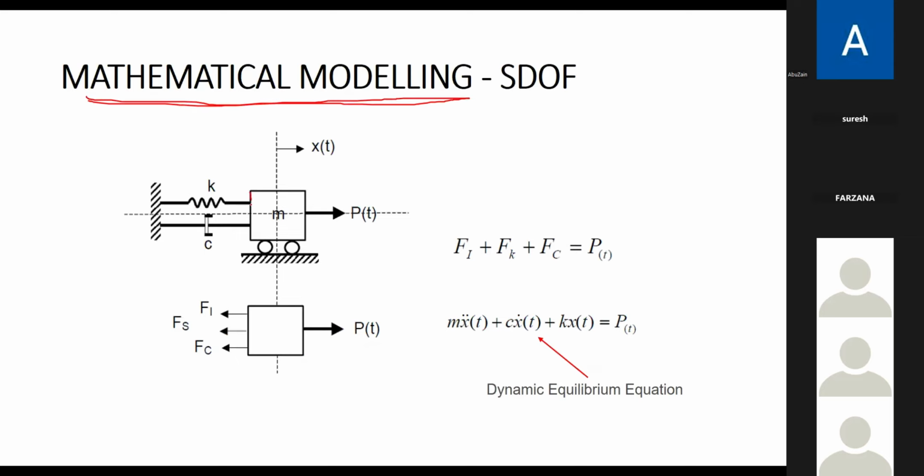Why do they say this? First they draw this mass. Why do they put a mass as a box? My mass is rigid. It's not going to deform. It's not going to deflect. This mass is going to move in x direction, so they put a wheel here. If it is like a roller support, this is going to move in x direction.